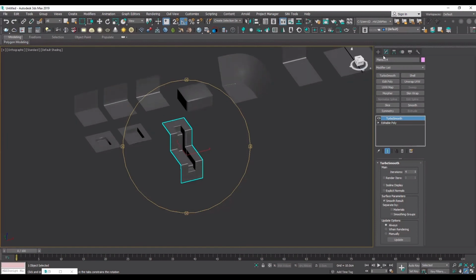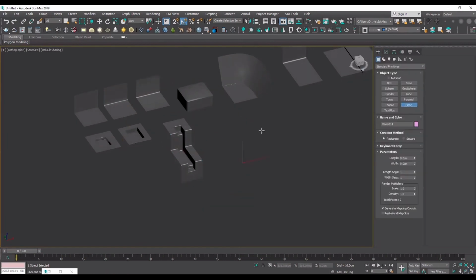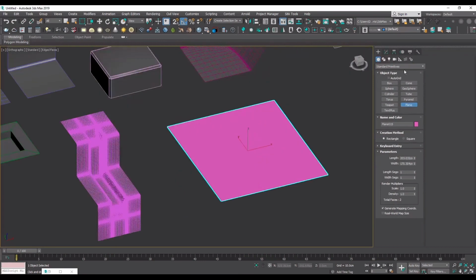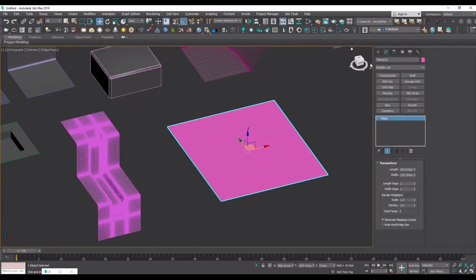But the most prominent thing with circles in hard surface models is that the octagon is going to be most of the time our go-to shape, because it's only 8 edges and has 8 sides. It's easy to control and so efficient for Turbo Smooth to soften into a circle.